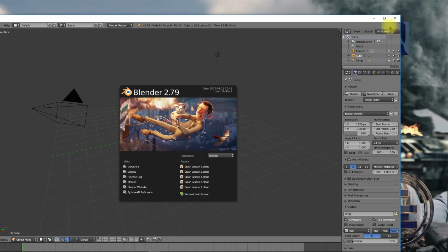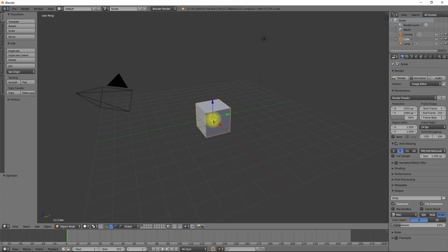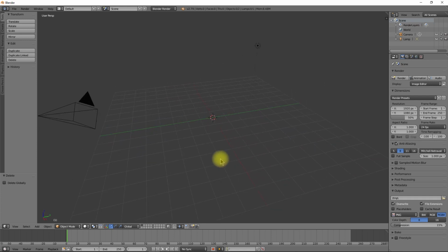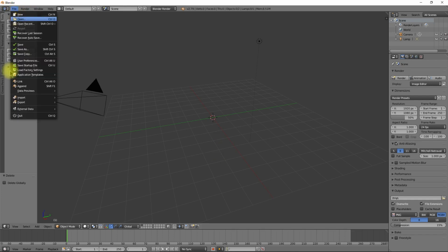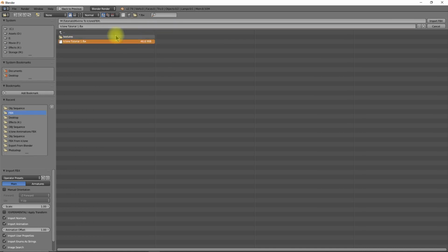All right, so let's open up Blender, and we're going to use that to create an OBJ file. Just right click, or left click, on the background, hit X, delete. Click on delete to get rid of the box, and now we'll import our character, the FBX file that we created. Import FBX under the File menu, and just click on it. You'll have to locate the file, so you go over to the left, and in my case I have it under tutorials. All you've got to do is locate your FBX, double click on it, and it will load up. You can see there's the path and the item, so it's telling you where it's getting it from.